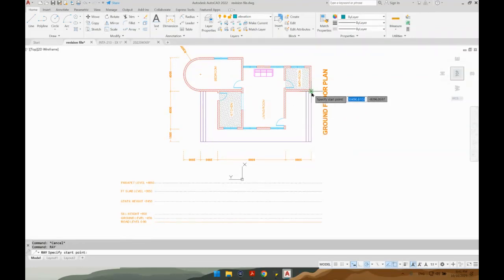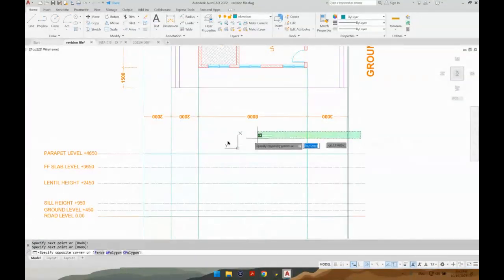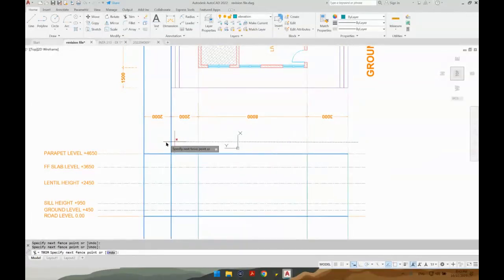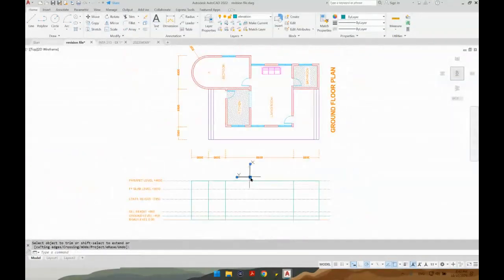So ray from here going down, 1, 2, 3. So beginning and end of each wall and each curve, by the way. So this one, all of them, everything that you can see. Then I will just connect the lines here and here. Select all the rays with these 2 lines, TR enter for a trim and remove them. I have my walls. Let me just remove this one. So I have my walls now.